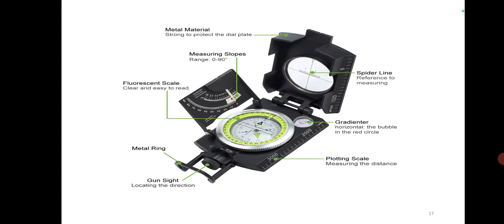This is like primarily geologists, archaeologists, environmental engineers, mining engineers, they use the Brunton compass. So this is actually a pocket type transit compass. It is highly accurate and mainly used to measure the dip and strike of the rock layers. And clinometer means you get the elevation, declination or depression. Okay, elevation, that is the vertical height. Then the slope, whether it is positive slope, that is as seen, that is upward slope or decline.